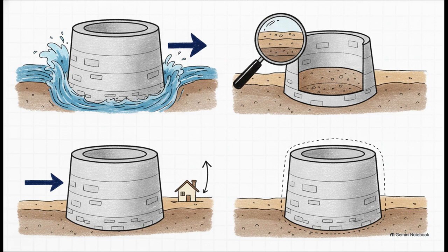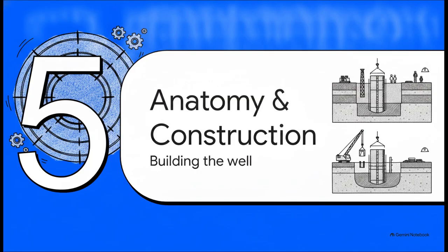There are some major advantages here. First, that sheer size and rigidity makes it incredibly effective at withstanding scour. Second, because it is open, engineers can literally inspect the soil as they sink it, ensuring they hit the absolute perfect bearing stratum. Third, it can withstand extreme lateral loads. Think of the powerful, relentless side-to-side forces from rushing river water or intense wind against a bridge pier. And finally, unlike driving piles which physically shake the earth, sinking a well causes zero vibration damage to any adjacent structures.